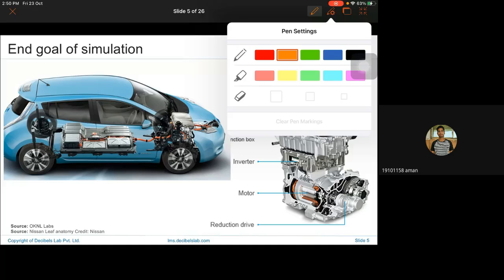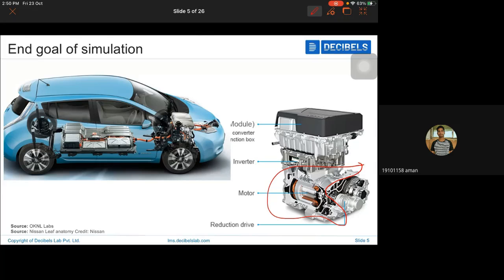You have a motor here, right? Then you have a transmission or a differential. Then you have an inverter, which is basically a motor controller. Then you have your power distribution module, which is basically also a DC-DC junction box. So basically, this is the charger to the vehicle, which you see here, sitting in place. This is a charging input, and then this is a big battery pack, which is sitting here. So this is how Nissan has put it all into place.